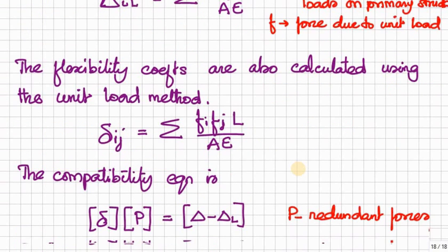Once we have these displacements due to external loads at each system coordinate and the displacement coefficients, that is the flexibility matrix, then we can apply the compatibility equation to get the redundant forces.